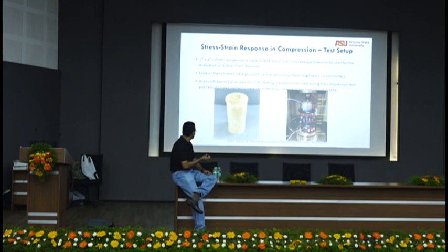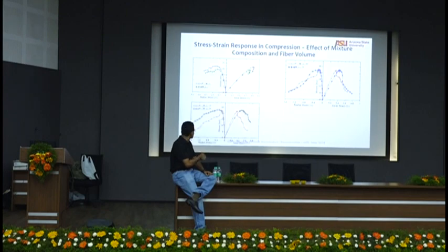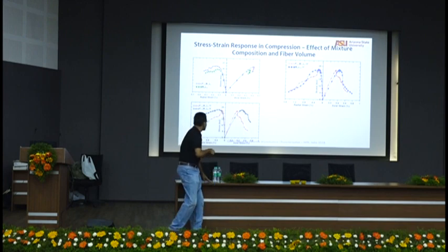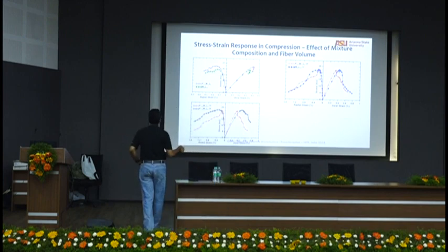So we did compressive stress-strain relationships. So here is stress versus axial strain and stress versus radial strain. It's a uniaxial test, just with triaxial measurements. So you push it, your axial strain in this direction, your lateral or radial strain in this direction. Again, the scales are different, so look carefully here.